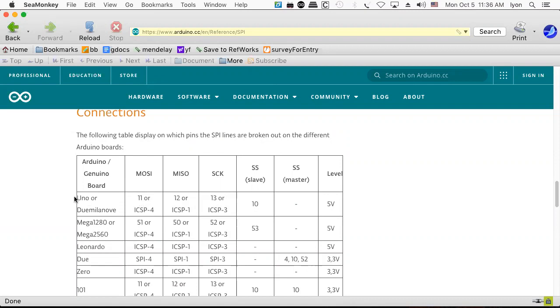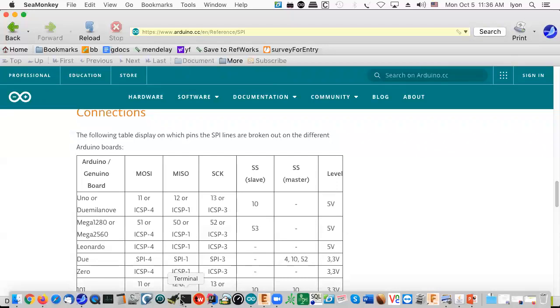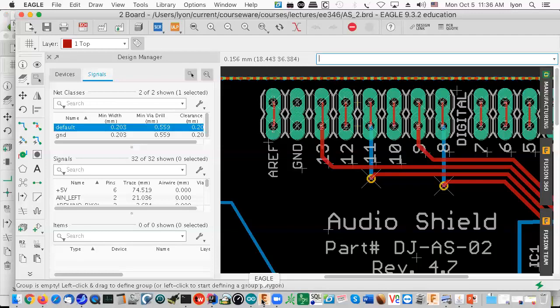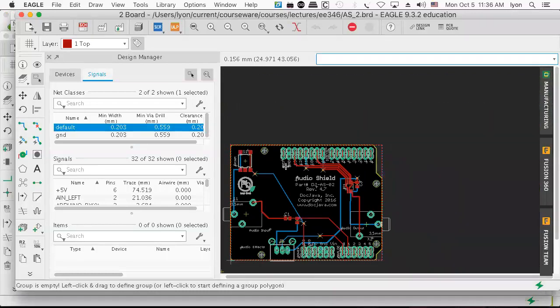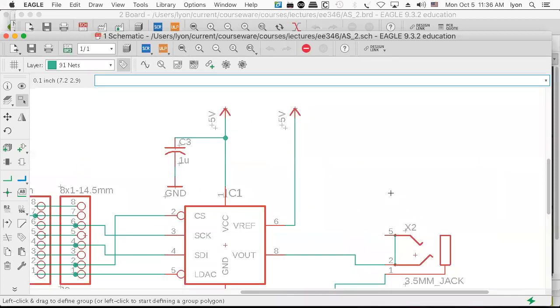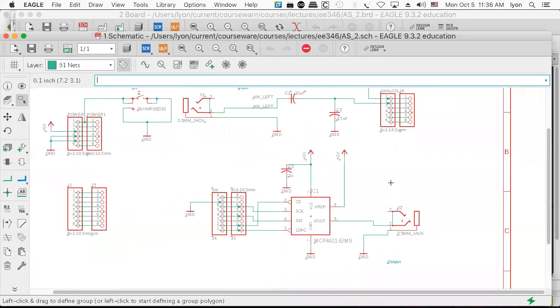That's cool. If you go back to Eagle, this is maybe a little more detailed than you like, but it's interesting if you're going to make your own boards. You can click in the upper left corner and switch to the schematic capture, and this maps directly to the board. As these things change, the board layout will change and you'll have to redo the routing when you go to make your boards. That's a cool thing.